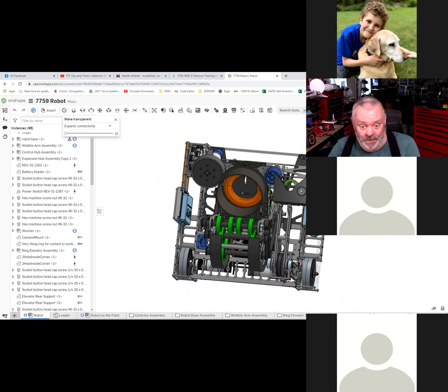The downside to it is if you have to play defense against another robot, for example, if they come and push on you up here, you're just going to get spun right around, right? In last year's game, we played it solo. We didn't have to worry about defense. This turned out to work out pretty good for us. I don't think I would have used these wheels if there's any chance of defense or a shoving match. But on the other hand, if you're just building something to drive around, it's not bad.